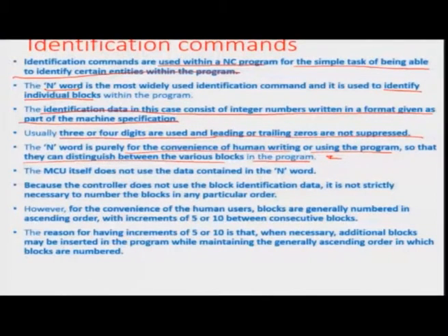So, they really do not need the command line number, but for a programmer who is on board, one needs to understand what corresponds to a command line and between which two command lines you want to specify some improvement or modification that you want to make to the code, and for that this N word is a very important aspect in the block itself. So, the machine control unit itself does not use the data contained in the N word; it is only for the operator and programming sake that this N word is being used.